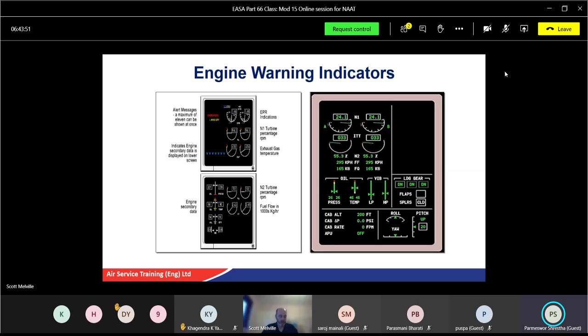Keyword, calibration. Trim resistor. That accounts for the properties of materials being used, from the thermocouples, the harnesses, etc. Although it's the exact same part number, they will have slight changes in resistance. So a trim resistor accounts for that and works for calibration.